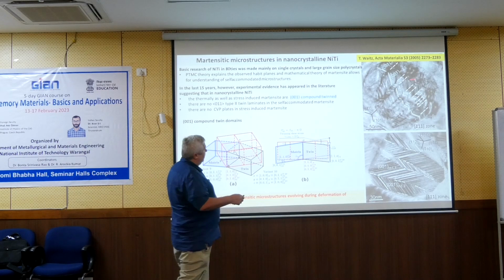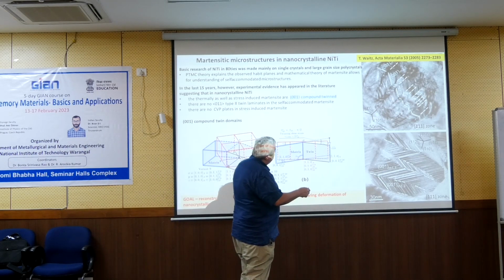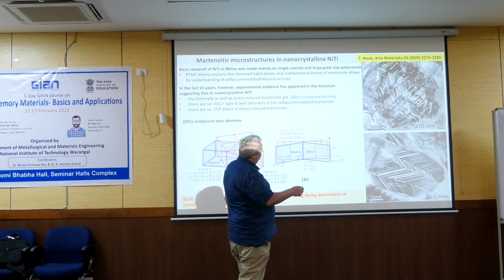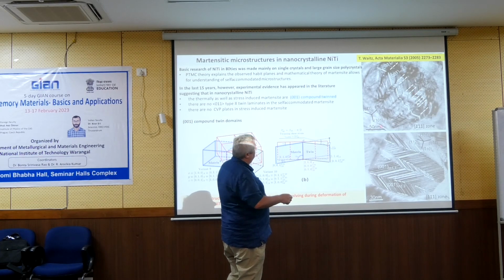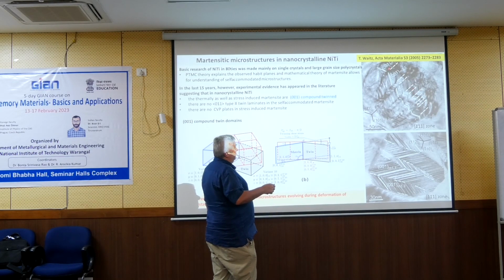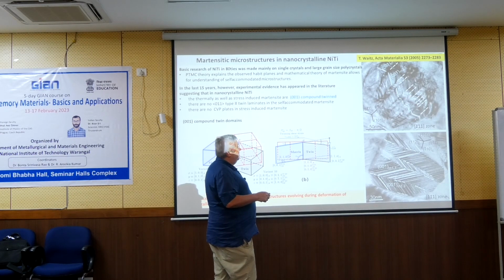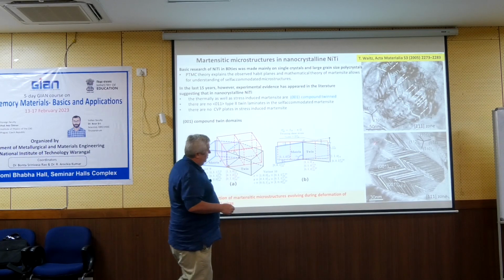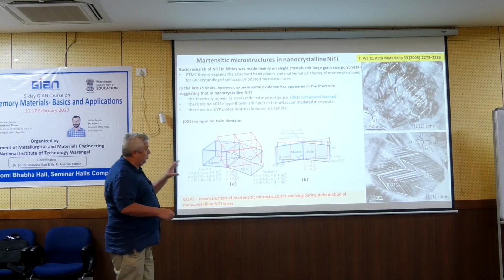In this microstructure there is a very fine lamellar structure. This is 50 nanometers, so the thickness of this twin is just a few nanometers, and there are some kind of families. There is no austenite, so there is no habit plane, but there is this microstructure, and this is what we knew of how such a microstructure looks after cooling.